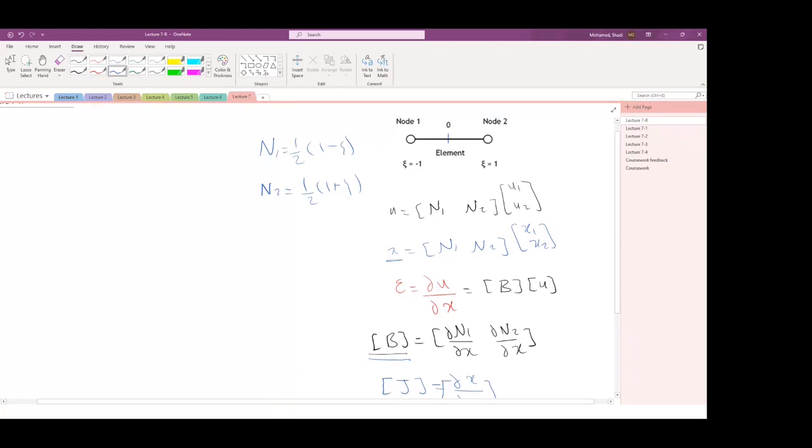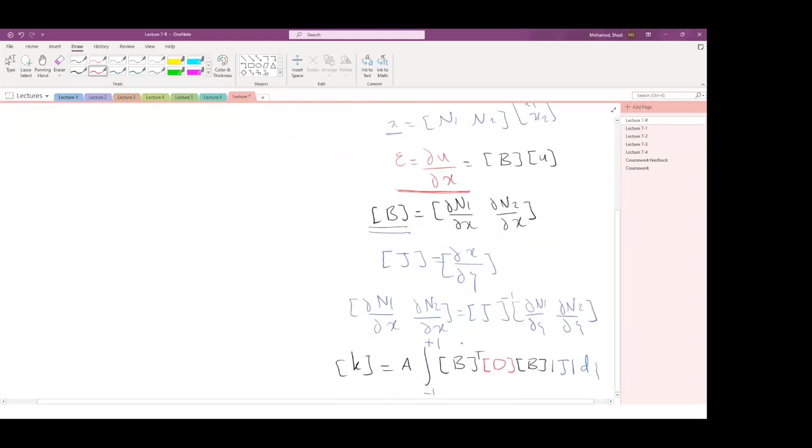The changes I'm going to introduce today are mainly related to the elasticity modulus, the strain and the material properties. So this constitutive relation, the elasticity modulus: we said the D matrix is simply the elasticity modulus. And this relation between the displacement and the coordinate is not going to be just u. First of all, you know that there will be displacement happening in 2 dimensions, so displacement in the x and displacement in the y direction. So just having a derivative with respect to x would not make sense. And the material properties are more complex in 2D than in 1D.